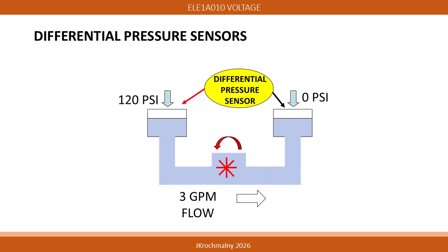We can measure pressure differences using a differential pressure sensor. Notice that when measuring with this type of instrument, 2 locations have to be sensed: the higher and lower pressure sides. The value on a meter records the actual pressure difference between these 2 points.